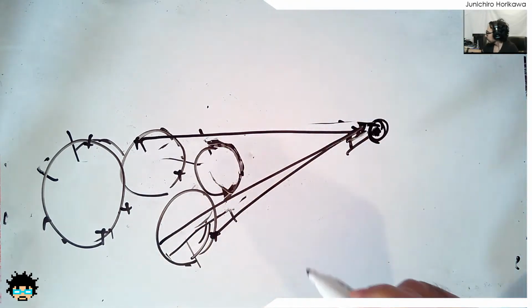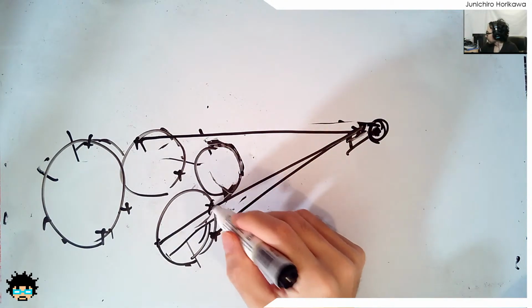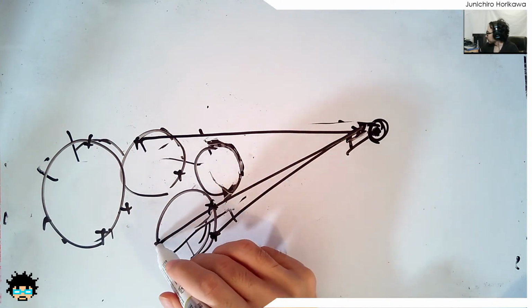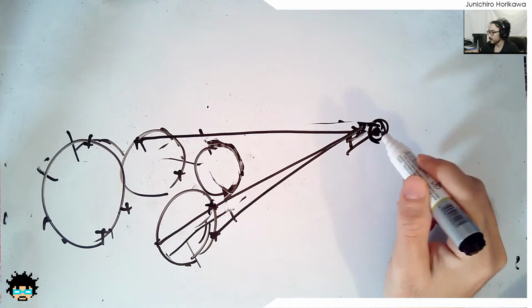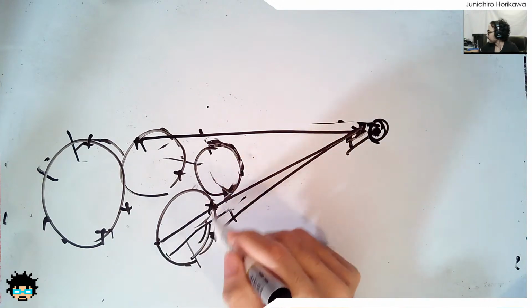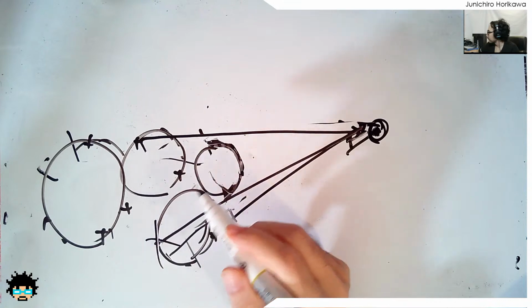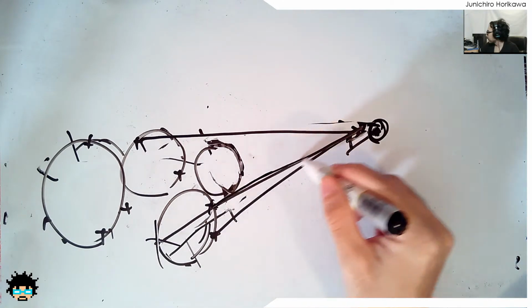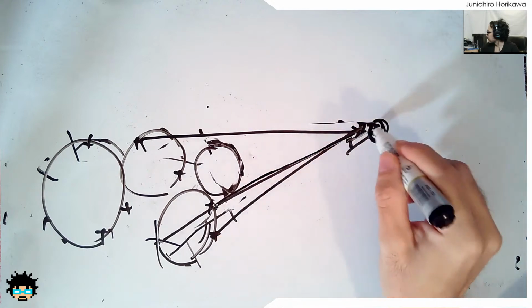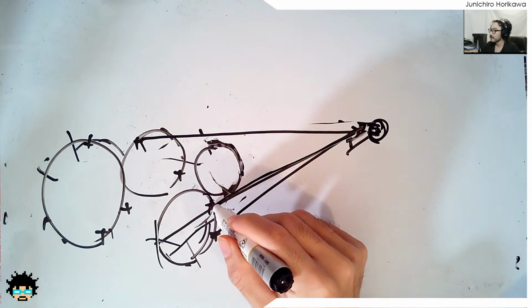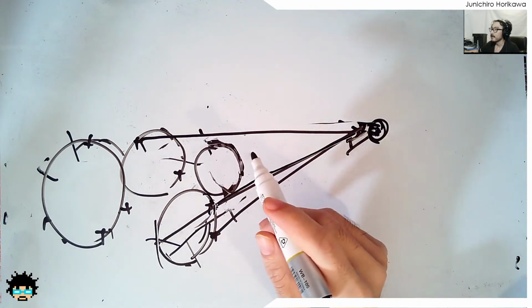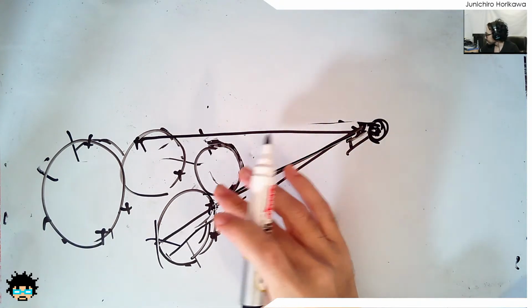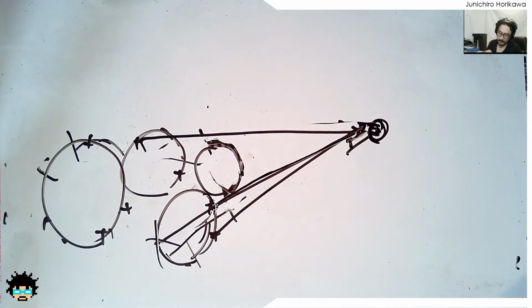Okay. So as soon as you find an intersection between the point position and the camera position, that means this point is covered by the front side, so you want to delete it. But if you didn't find any intersections between this point and the camera position, then this point is at the front side, so you can keep this as a front side. So that's how I'm going to determine whether the point should be deleted or not. Right? So let's try to do that.